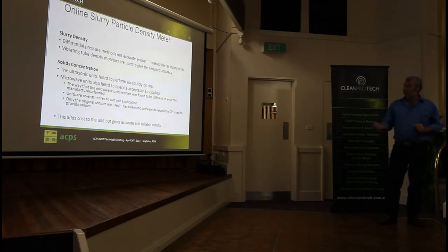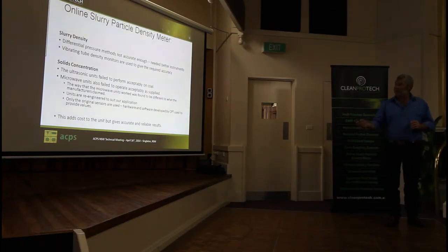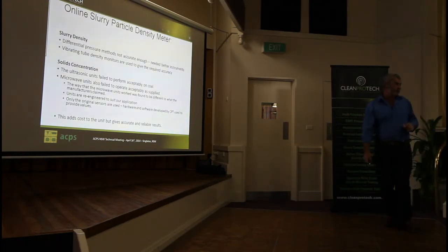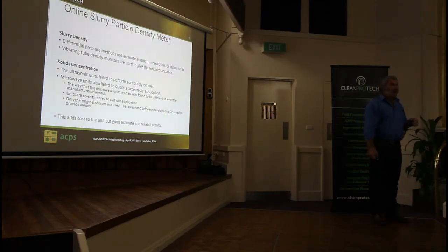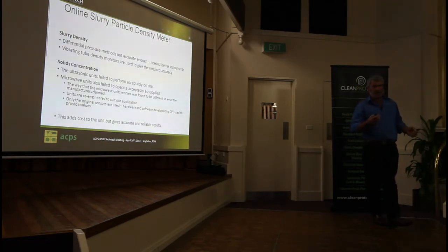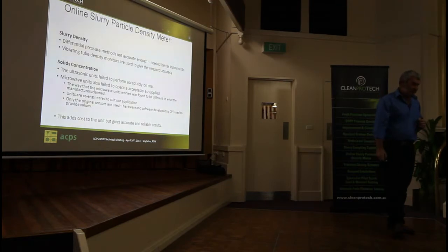Now, slurry density. That turned out to be quite tricky. Again, don't forget, we've got to look at the accuracies we need for this device, which is quite tight. Quite a lot of mathematics involved. Differential pressure was not accurate enough for what we wanted to do. Nucleonic, one we wanted to avoid. Ultrasonic, again, not nearly accurate enough for what we needed here.